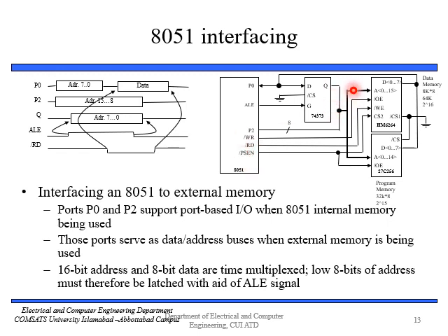This is linked to our data memory, 0 to 7 you can see, and the addresses are 0 to 15, and this is our program memory and the addresses are from 0 to 14, and this is 0 to 7. Here the timing diagram is shown for the data memory. The addresses and data are multiplexed.